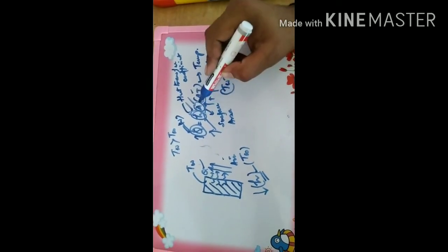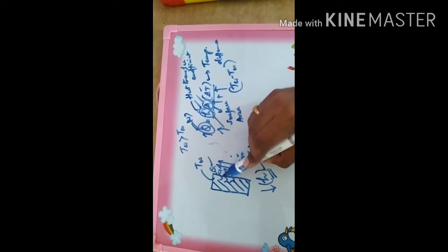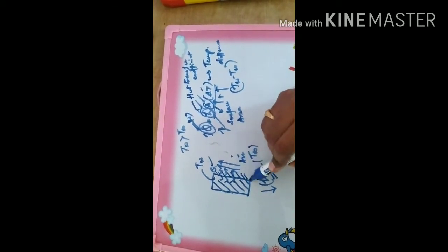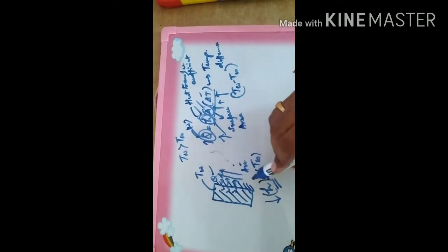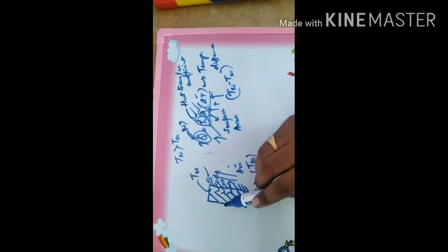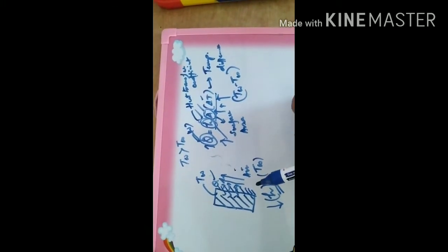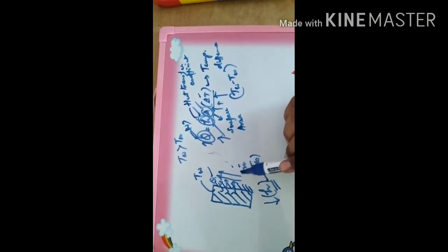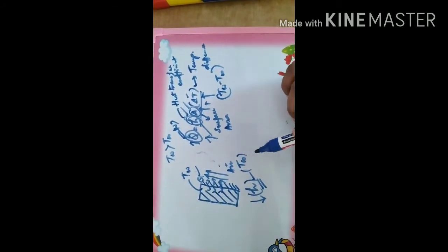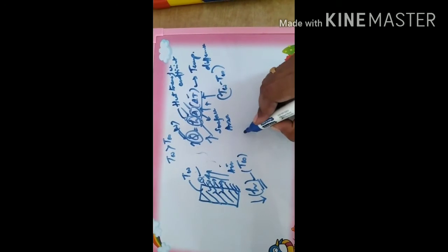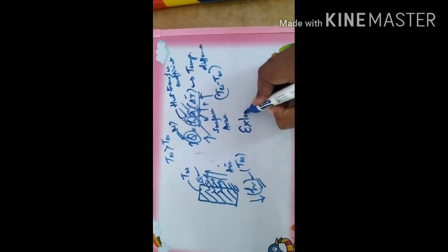So what is this area I told? It is this surface which is coming in contact with the air. So if we can increase this area, then we can say the heat transfer from the surface to the air will be increased as per Newton's law of cooling. So here is a point where we will come across an important topic called extended surfaces.